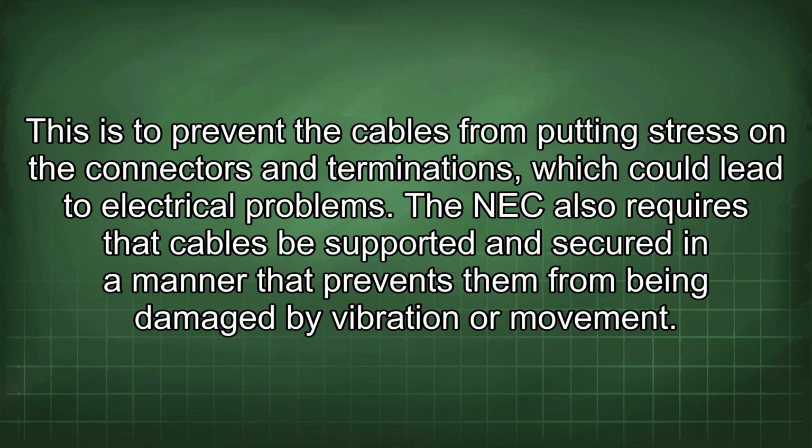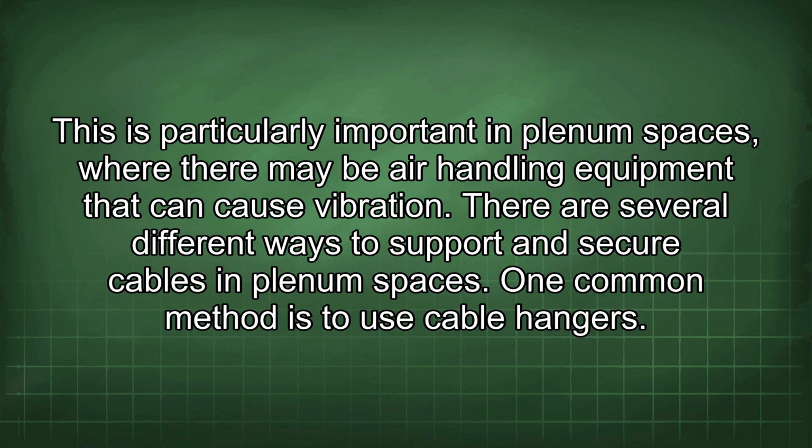The NEC also requires that cables be supported and secured in a manner that prevents them from being damaged by vibration or movement. This is particularly important in plenum spaces, where there may be air handling equipment that can cause vibration. There are several different ways to support and secure cables in plenum spaces.